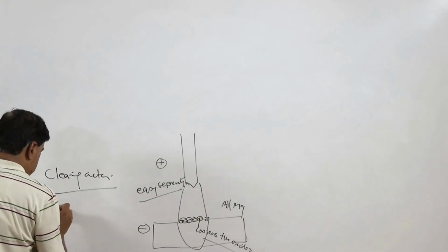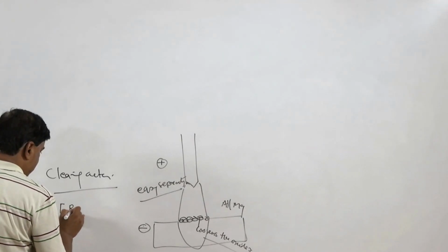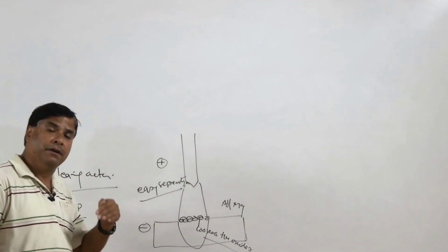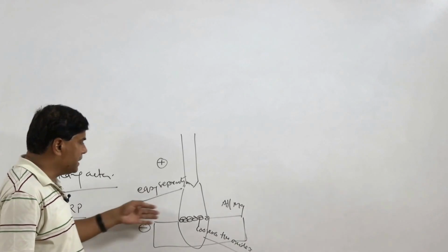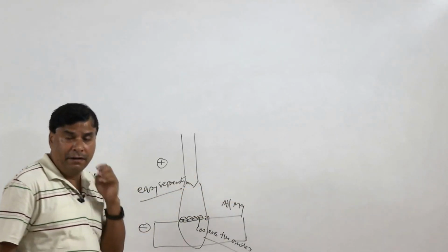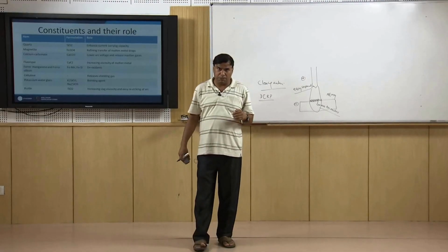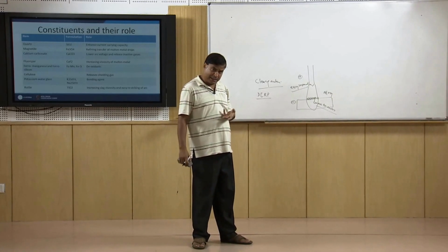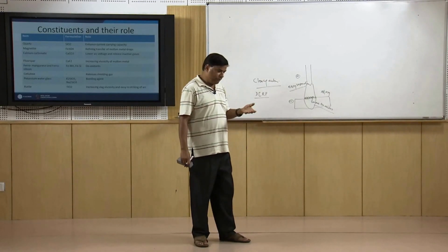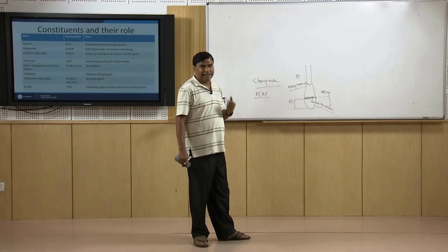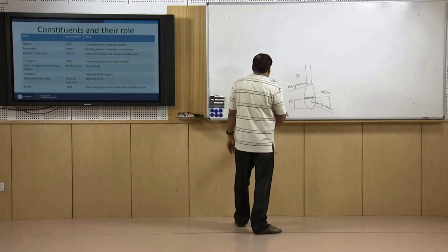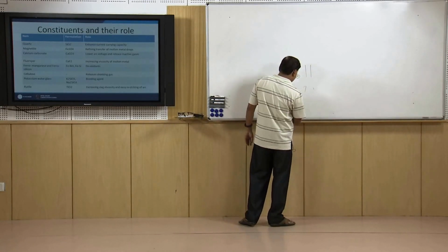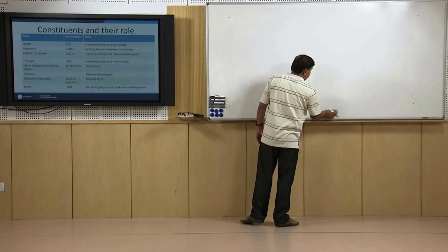So, the use of DCRP is intentionally used sometimes to exploit this concept of the mobile cathode spot formation, especially in case of aluminum and magnesium welding, because the formation of the mobile cathode spot helps to loosen the oxide layer, and the loosened oxide layer starts floating over the surface of the weld metal and thus it can be separated easily, which in turn will help to clean the weld and produce cleaner weld metal.